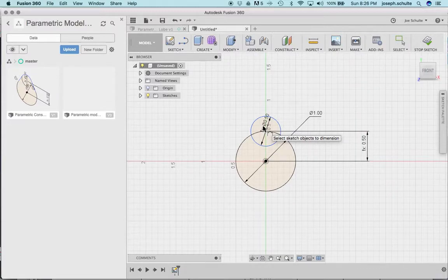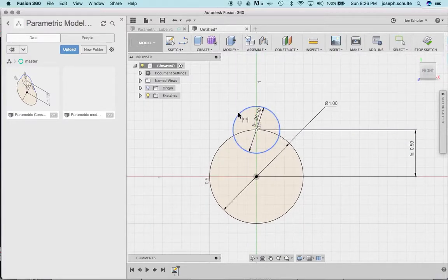Now, what I had trouble with figuring out is the way to get a tangent line to go from a line that's tangent to this circle to go to this tangent point on this circle. And what I figured out by trial and error is I hit the line key. If I choose up here at this 1 inch mark away and go to this tangent point, click, hit the line key again, go from here to here, I get another tangent line.